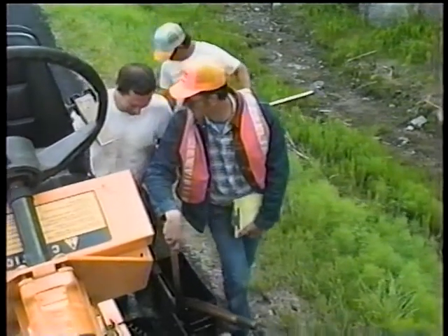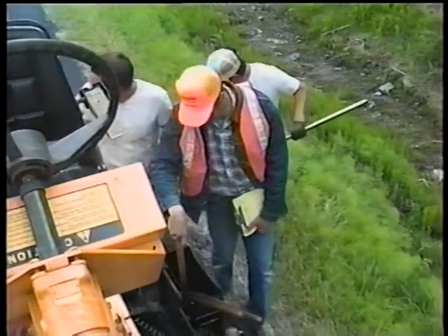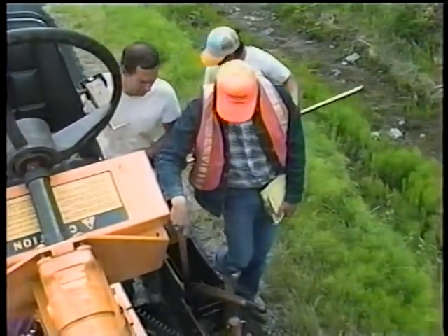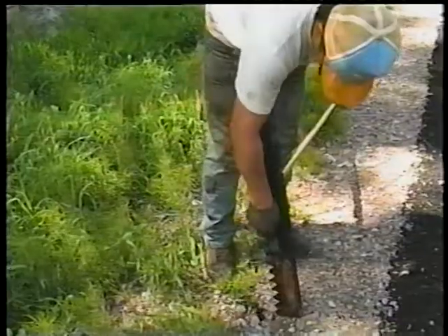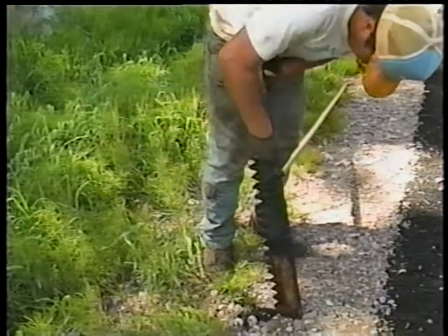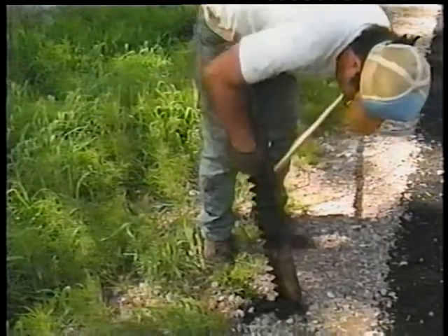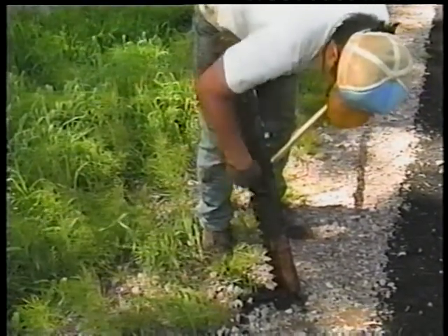Just one more point about hand tools. Most contractors store them in containers filled with diesel fuel. That's perfectly acceptable as long as the fuel isn't spilled on the mat. While the hand tools are in use, however, they should be cleaned with a putty knife, not with the diesel fuel. And they shouldn't be cleaned by scraping them off on any part of the laydown machine either.